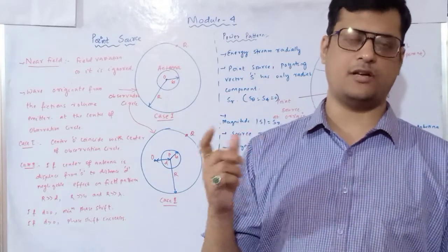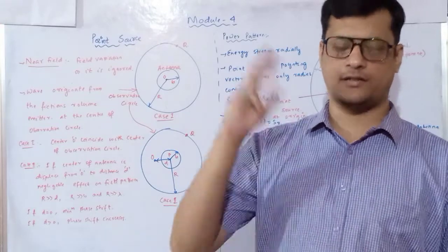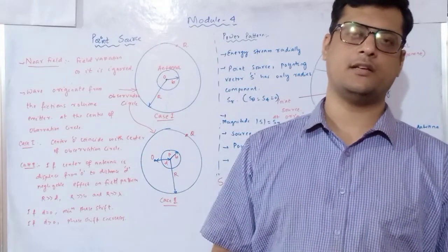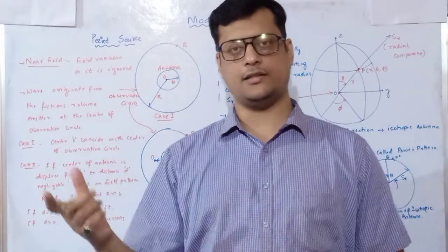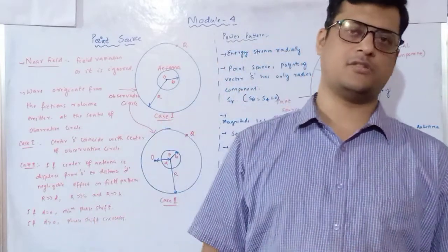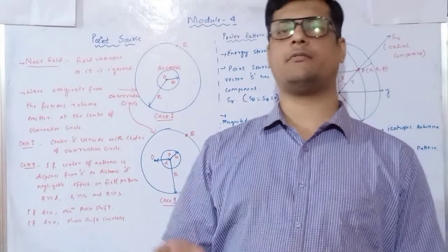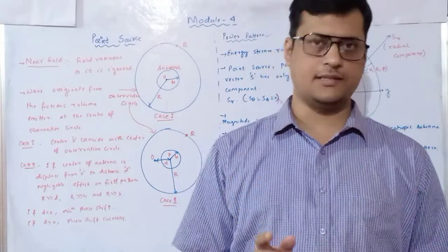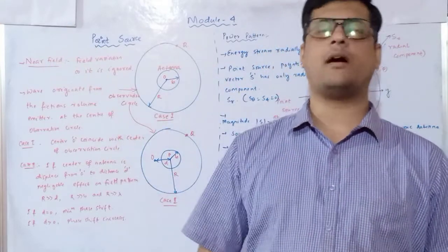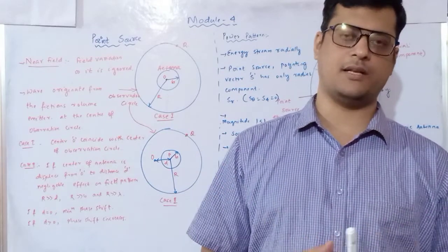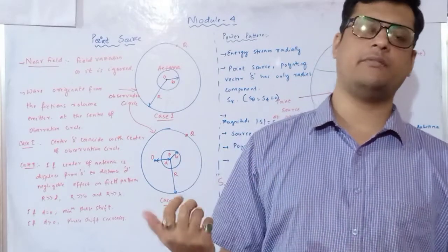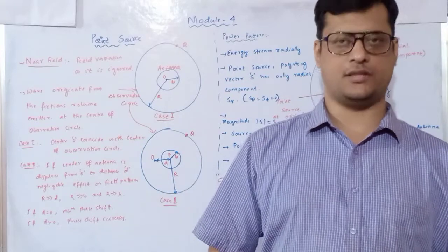The second region is our Fresnel region, and the third, the far field region, is also called the Fraunhofer region. According to the distance we are going to measure. Basically the variation of electric field and magnetic field is very small when we are measuring in the far field. So whenever we measure some points or some intensity, we measure at far field positions.